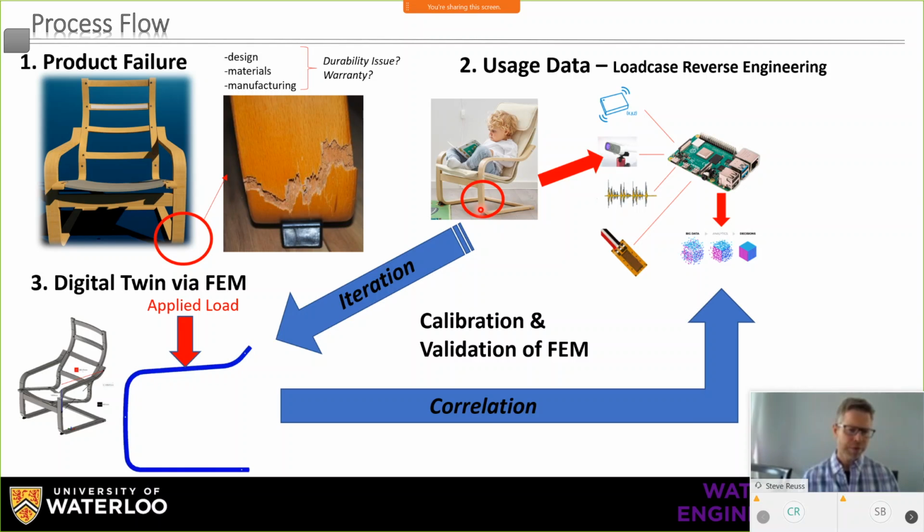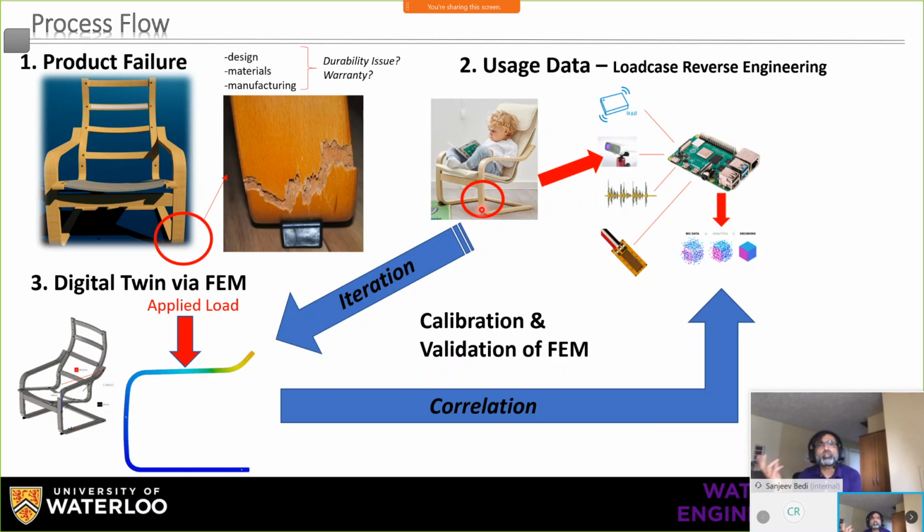And we can obviously look at the video to validate that. But in terms of the center of gravity of the loading and the intensity of the loading, we could put maybe even a load cell underneath the platform that the chair is sitting on. That might be a good idea. But this is really where the project's still in the development phase. So it's a great question that you asked. And Steve, you're talking about the inverse, where we know the displacement and we have to figure out the loading that causes the displacement. I think that part we have not emphasized in this particular setup. That will be between stage 4 and 5, but it'll have to be done because it's a chair. I think we could do it very simply.